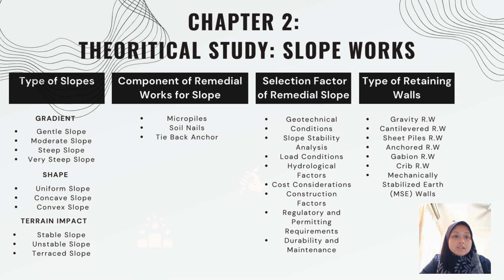The soil nail is a passive inclusion installed into the soil to increase its stability. They are typically long, slender elements like steel bars inserted into pre-drilled holes and grouted into place. The main function of the soil nail is reinforcing the soil by increasing the shear strength, limiting deformations by providing additional support, allowing the wall to retain more soil and distributing load.